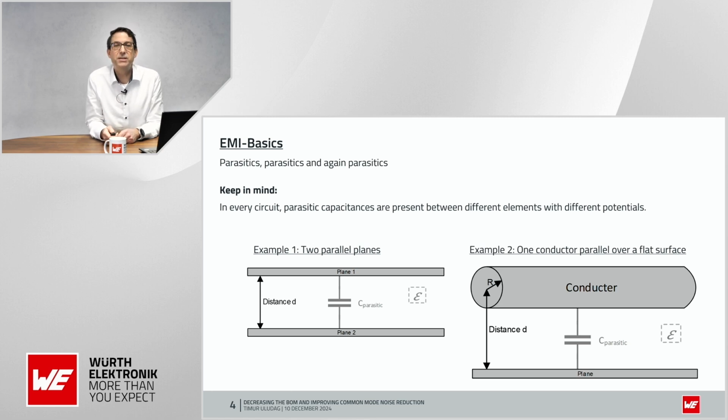What is a parasitic capacitance? If you take the power module, as you saw on an evaluation board, you put the input cables, the output cables, the load and everything, and make a reference surface out of it, then you have something like two parallel planes that form a capacitor.